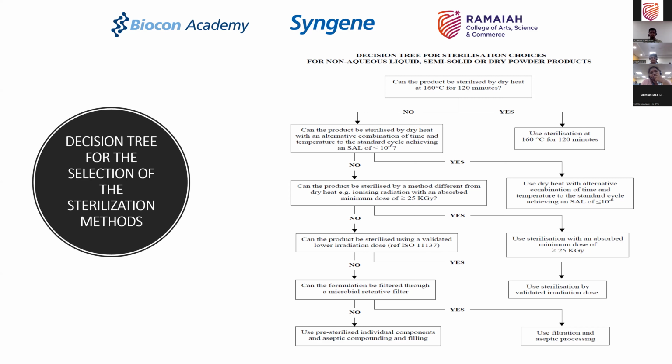So if you look at the decision making tree, the reason why they prefer terminal sterilization is also because when you get into certain formulations and certain manufacturing of components, you will find that the number of unit operations may force you to have sterility assurance at different places, which is not always an easy task. And of course it is possible, you can have techniques to do it, but then it affects the cost of the product and the time taken to manufacture the product.